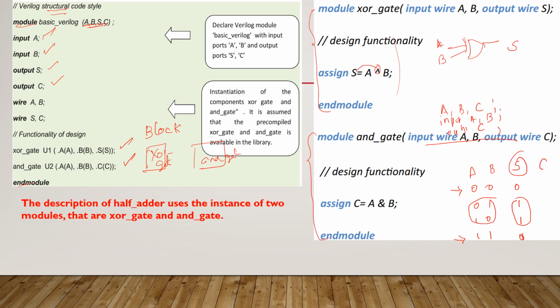For carry, you know that it is 0, 0, 0. If 1 and 1 are added, you will be getting 10. So 0 will be put at the sum and carry at the carry. In this, you can compare the inputs with the carry output. Which gate is required to design your carry? It clearly shows that you get the output 1 only if both the inputs are 1, 1, right? Only then do you get the output 1. In all other combinations you get 0. That means it is obviously the AND gate. So this is the AND operator. You have to use A and B.